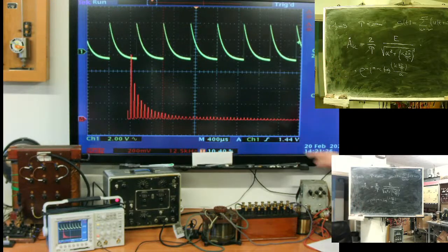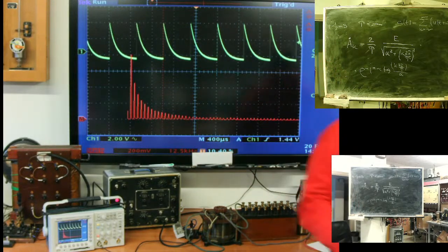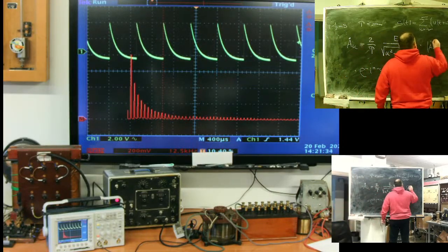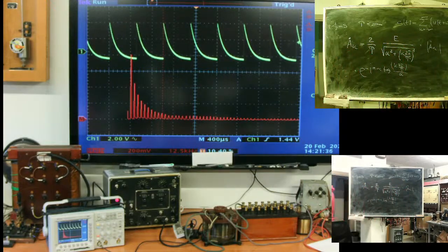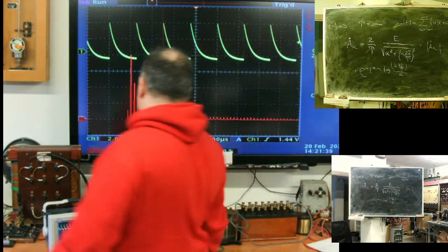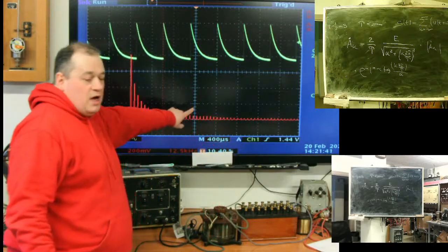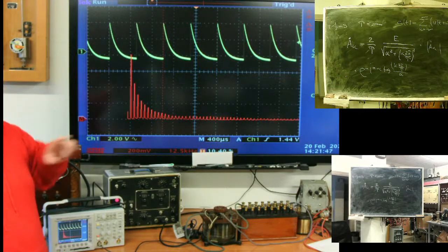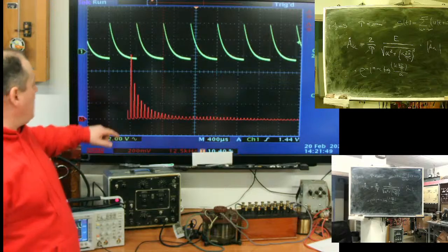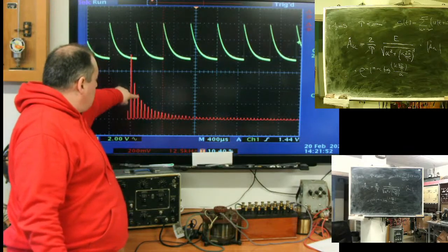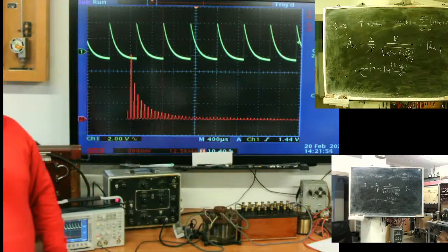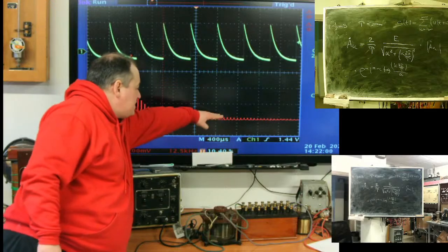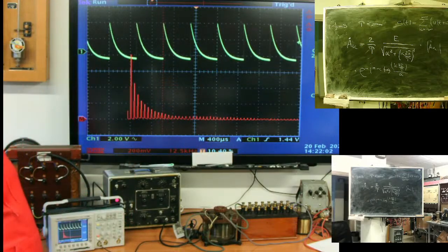The red line, can you see the red line? It shows absolute values of frequency components. Here, the red line is a representation of my signal in frequency space. The spectral function, if you connect all these points, will form kind of borderline or limit line. If you connect like this, it will be a spectral function.